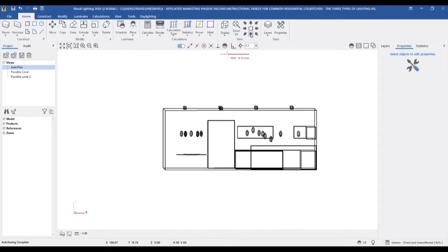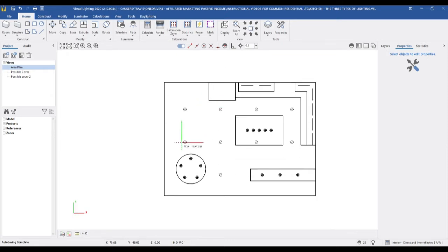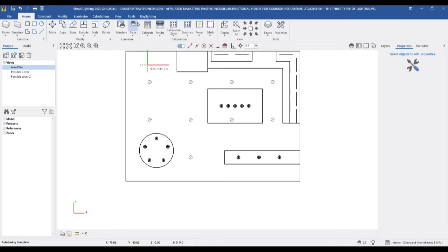In a kitchen, if you usually have an attic access above your ceiling if it's a remodel, or floor joist space, or any of the above if it's new construction, then can lights are typically the best way to do this. A lot of contractors will use 6 or 5 inch fixed cans, or if it's a sloped ceiling, they'll use 6-inch sloped, or there's 5-inch adjustable cans that they'll use.